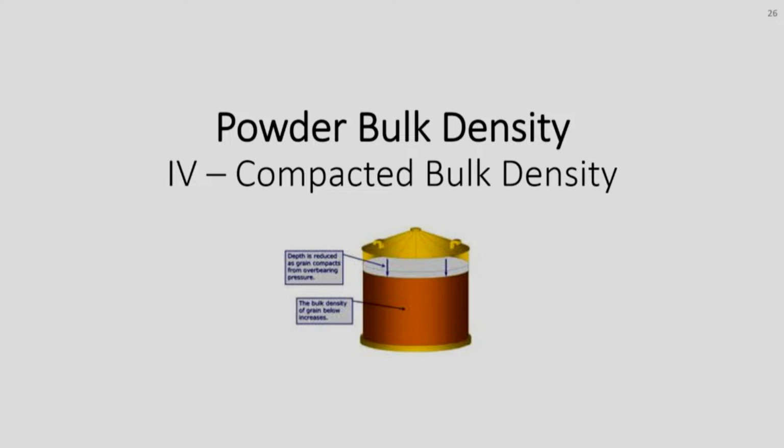So that's again one common place, at least in food and grain, where we use it to get the actual amount of material, due to this change in density. Same thing for shipping too. Inventory: for inventory calculations, how much material you have in the bin, you'll have to use the compacted bulk density.